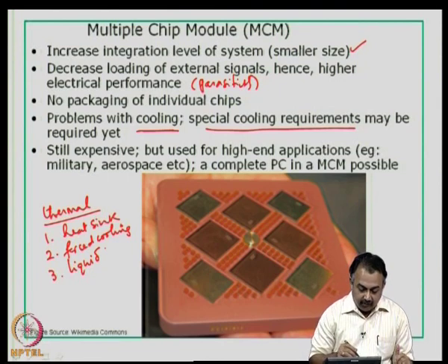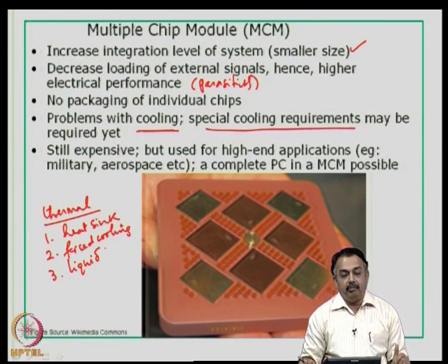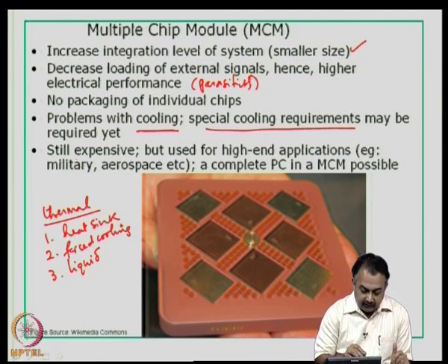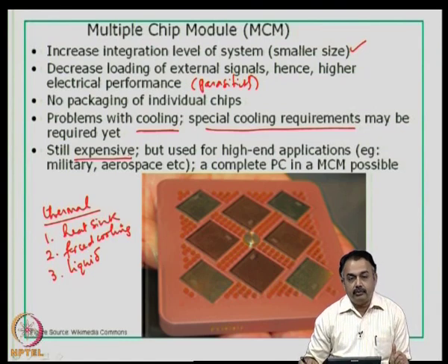Therefore, thermal management becomes an important topic in the design of multi-chip modules. Therefore, it could be expensive compared to looking at a chip on board configuration or simply assembling different single chip modules on a common substrate.